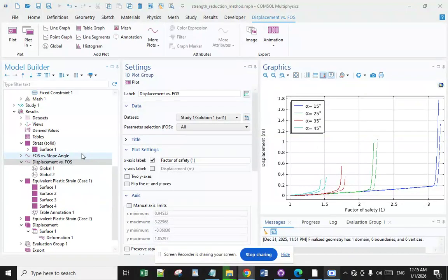The field of aerospace engineering uses generally lower design factors because the costs associated with structural weight are high. For example, an aircraft with an overall safety factor of 5 would probably be too heavy to get off the ground.